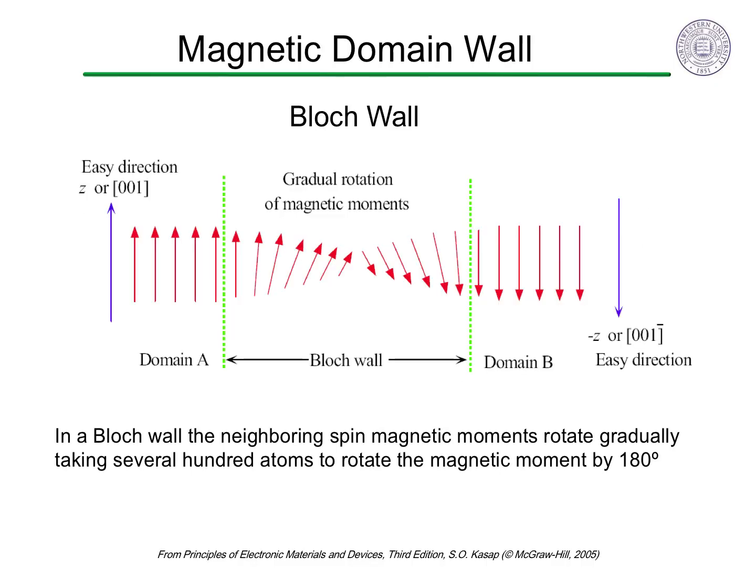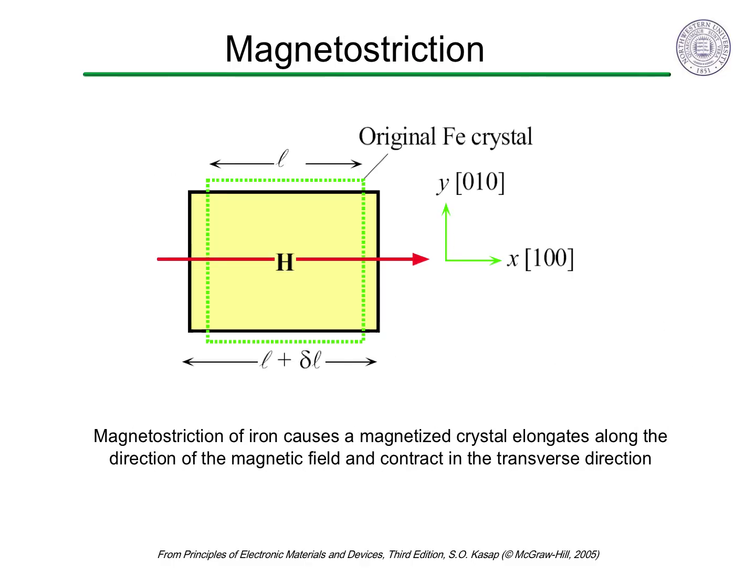The domain walls themselves are not usually atomically abrupt. A gradual rotation, such as the Bloch wall of several hundred atoms, has lower energy by keeping neighboring atomic interactions largely ferromagnetic. When a material is magnetized, it produces a small amount of strain called magnetostriction. Although small, it leads to some inhibition to magnetization and demagnetization due to strain energy.